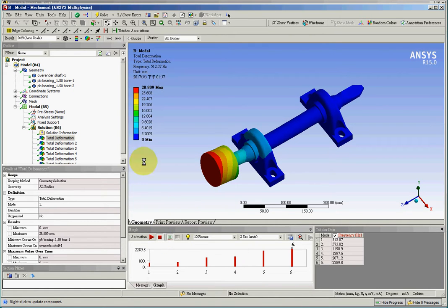You have to be aware that when we increase the mass of a structure, we actually decrease the natural frequencies, because the term mass appears on the left hand side of an ordinary differential equation, and the force term, external force, appears on the right hand side of the differential equations. So in natural vibrations, the effect of mass is quite different from the effect of external force.